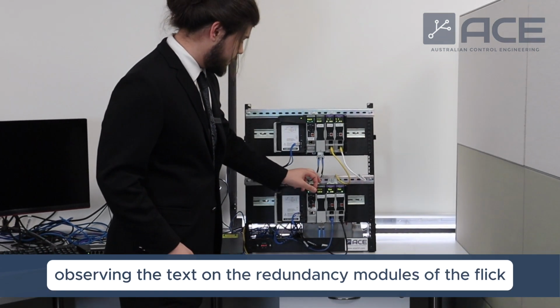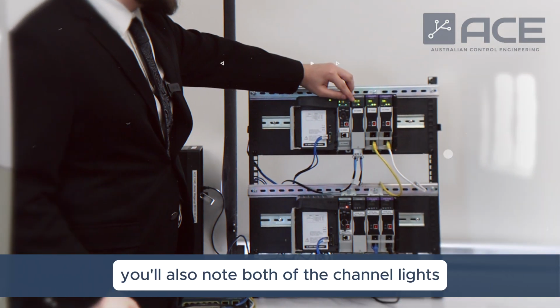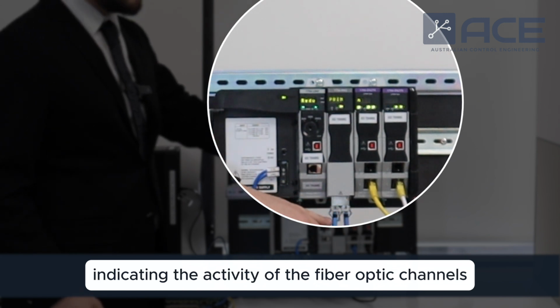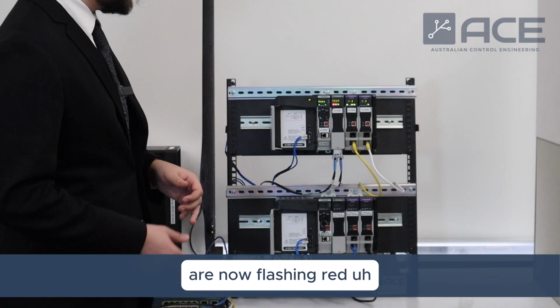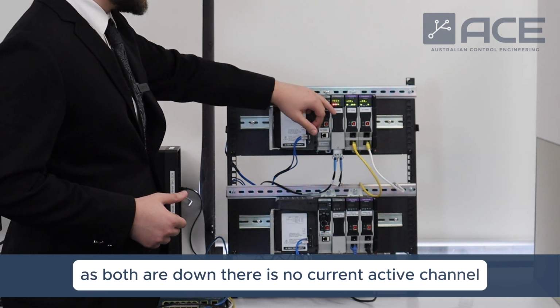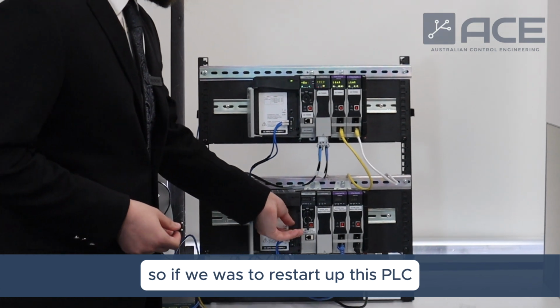So observing the text on the redundancy modules as I flick the power supply on. And you'll also note both of the channel lights indicating the activity of the fibre optic channels are now flashing red. That's another way of indicating that communication has been lost on both channels. As both are down, there is no current active channel. So if we were to restart this PLC,